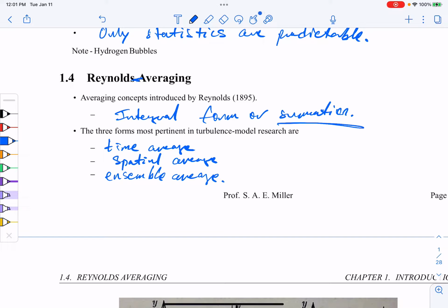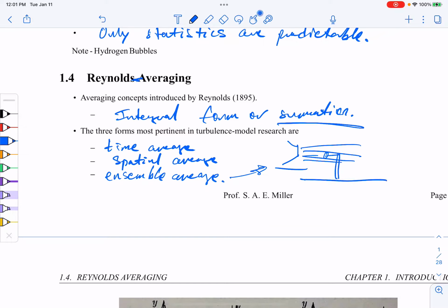It'd give me some intermediate value. And so an ensemble average is probably the most general type, where I take a number of averages. Where a rocket engine is starting is my favorite example, and I put the probe here, and I would take, say, an average n1, 2, 3, 4, etc., and I would take all these and find, say, u bar at time equals 0.001 seconds. And I would do that for the same engine maybe 40 or 50 times to find a startup value.